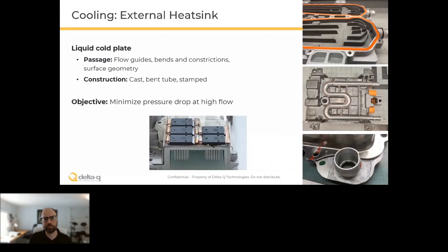If a vehicle or a machine has a liquid cooling system, it was probably designed and sized to cool larger loads like the traction motor and the battery pack. Those can be very high power, so it can be quite a high capacity system, typically quite high flow rates. And then the battery charger may be sourced later and plumbed into the system as an afterthought.